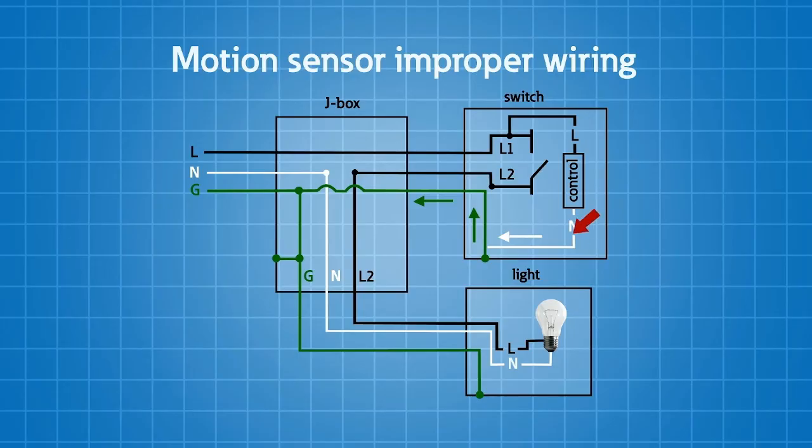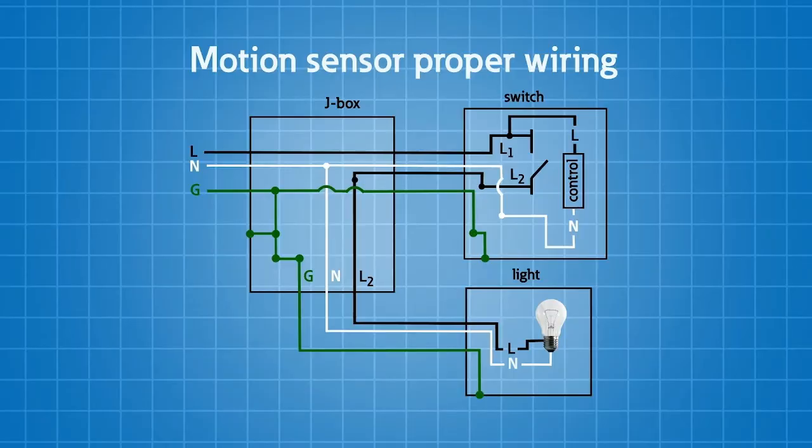But it would put current over the equipment grounding conductor. And based upon the definition that we just created and just talked about, that would be current flowing on the equipment grounding conductor that's not because of a faulted condition. That would be what we call objectionable current. And that is not permitted by the National Electrical Code. So changes have occurred over the last few cycles, one, to prohibit the use of those products, and two, to require the pulling of a neutral at those switch locations.